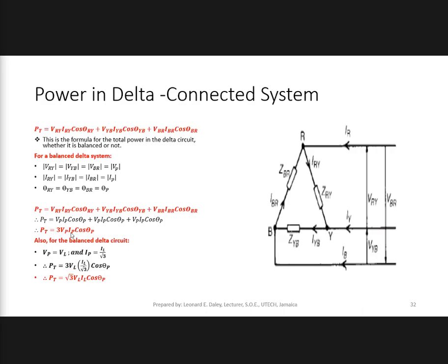So the power factor is giving you a measure of how much work you can get out of a certain amount of apparent power. And when you say apparent, you apply a certain amount of voltage and you see a certain amount of current flowing. So in all practical purposes, you expect that whatever you put in, you should be getting out.